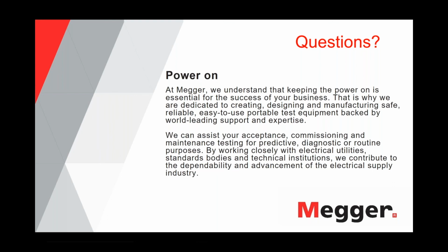So many times, however, what the real issue is that when you have a paper insulated circuit, you many times have old and new mixed together. So you have belted and non-belted cable in the same circuit. And the only thing you can measure then is the total dielectric loss in this cable, because you cannot differentiate.